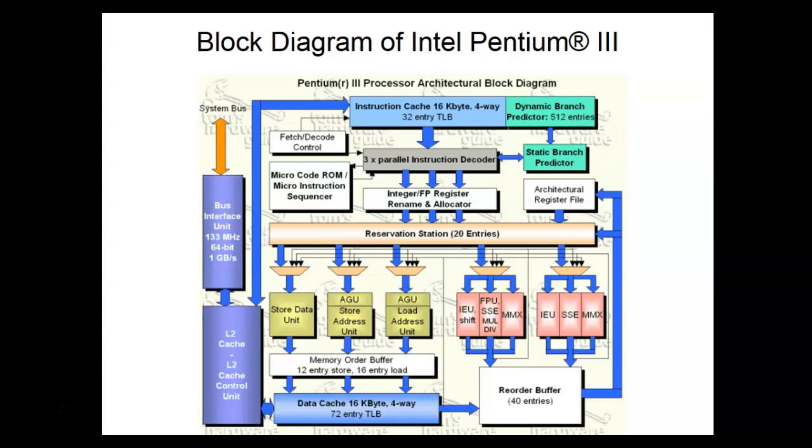So with DDR, what they realized was that on the clock, we used to transfer data on just the rising edge. Well, they figured out a method where they could transfer it on the rising edge and also the falling edge. This became known as DDR for double data rate because it could transfer at twice the speed. And then they came up with a method of staggering the memory. So you notice the little memory slots are different colors.